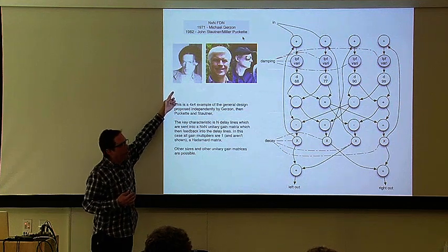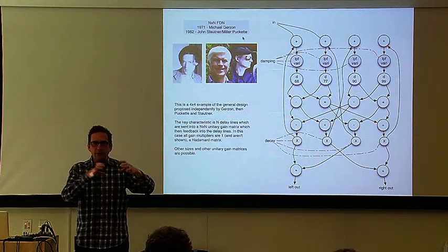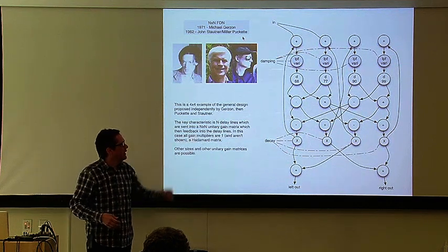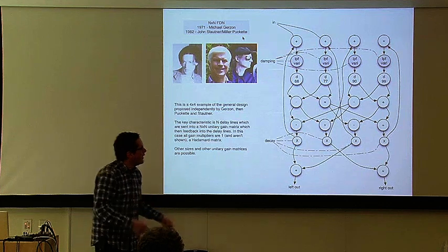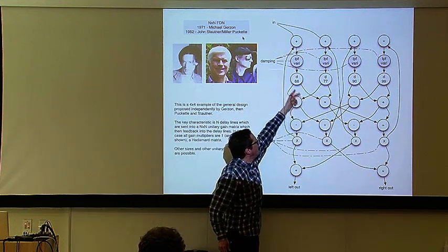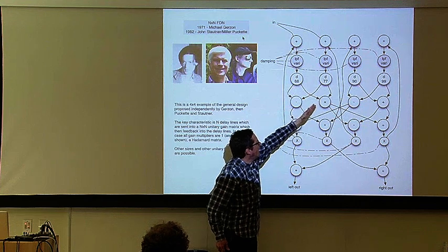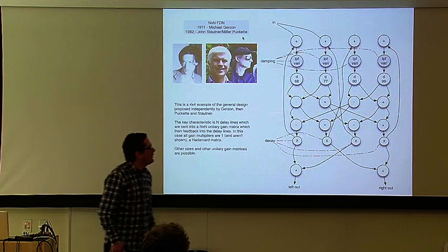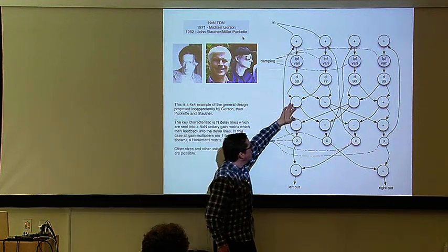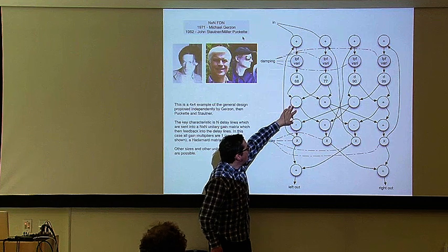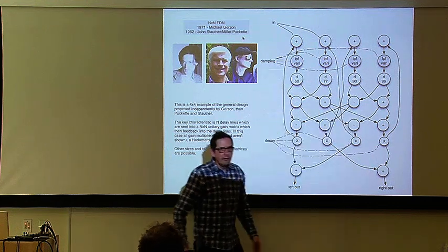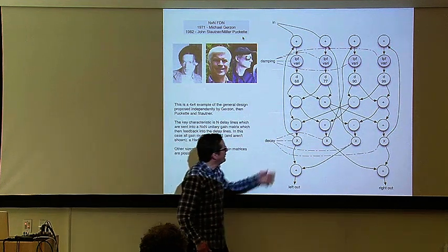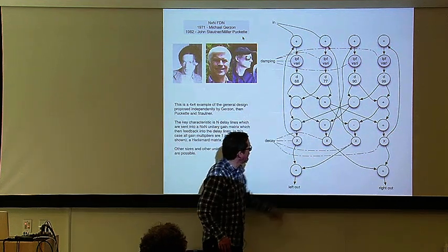He was really talking about linking multiple analog delay lines together and using analog matrices to create this cross feedback. What we have now is 4 delay lines going into a matrix where everything feeds back into everything else. The other thing is that this is a unity gain matrix, so we can actually control the feedback. This is the Hadamard matrix.